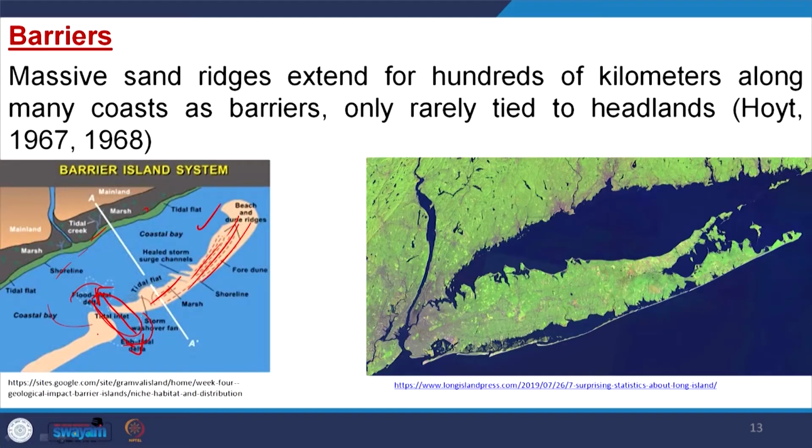And this is a satellite image. If you see here, this is the barrier it is generating, and one barrier is again divided into two different segments. How does this happen? Either two barriers will coincide to form one, or one barrier will divide into two. That depends upon the mechanism of sand supply, the wave action, the tidal action and the river action, like that.